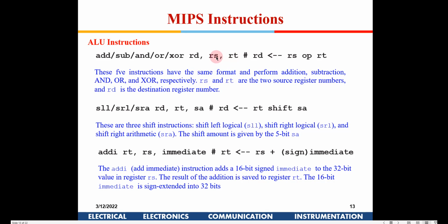The net result will always be in a third register, so there's no data destruction happening here. You're not losing any data in these kind of instructions. The result is always stored in the destination register, which is different from the two registers on which the operation is being done. So that is one of the major differences between 8086 and the MIPS instructions.